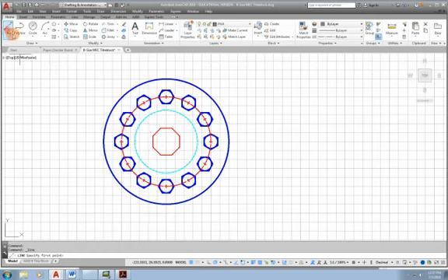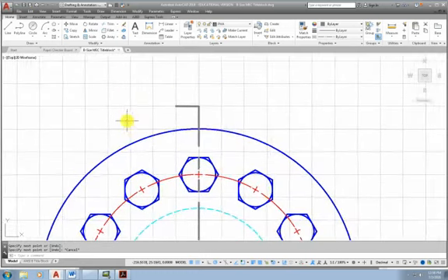And so what I'll do is I'll come over here, I'll turn my snap back on, F9, and I'll just draw a line right through the center. And then I'm going to bring it like this, hit escape, repeat line. That was a right mouse click. And then for the arrowheads, I just draw them and use a fill pattern. And so what I'll do is I'll come back here, I'll go like this.